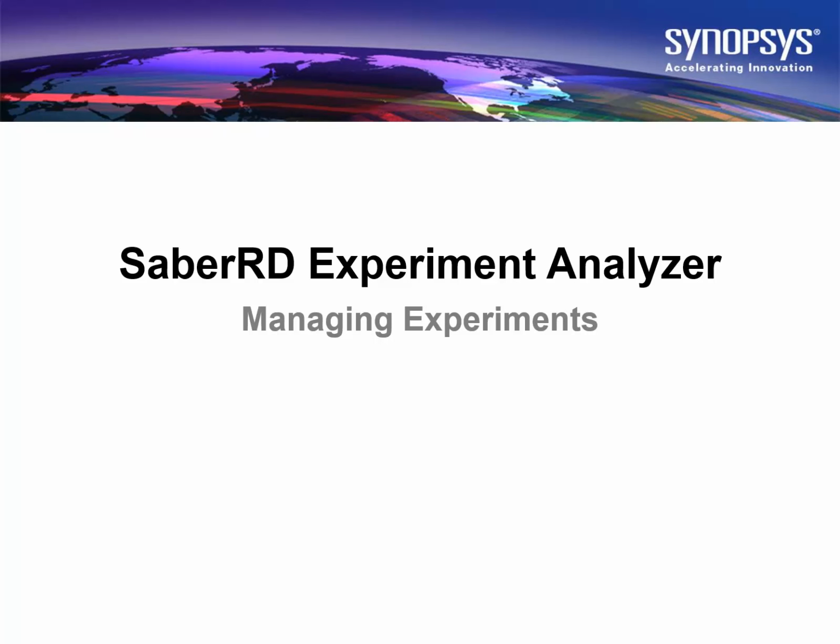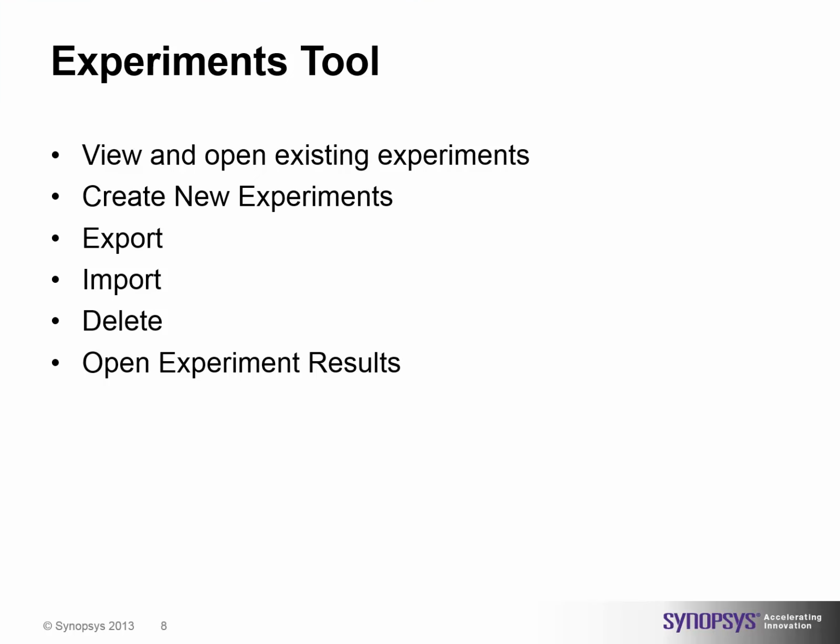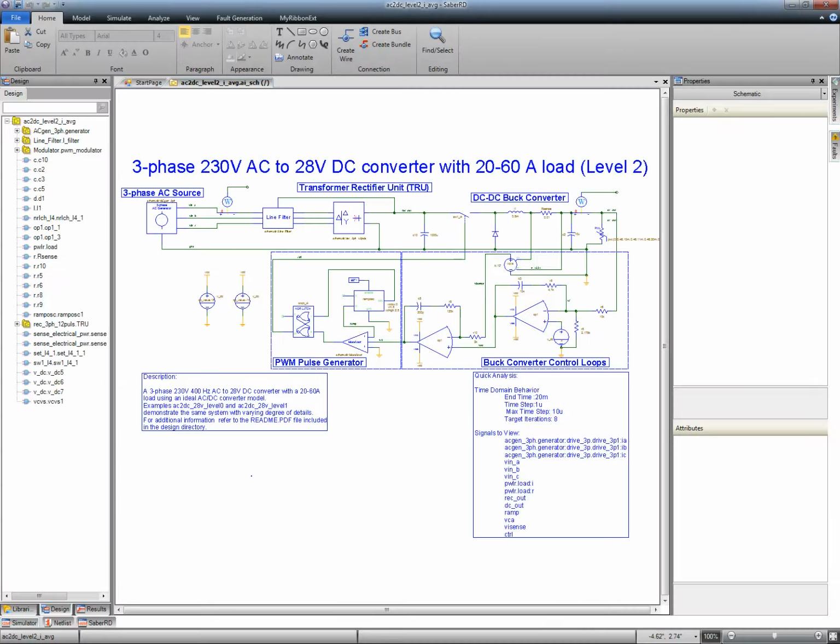Managing experiments within SaberRD is straightforward using the Experiments tool. The Experiments tool is where you view and open existing experiments, create new experiments, export and import experiments, delete experiments, and open experiment results. Let's take a look at how this is done.